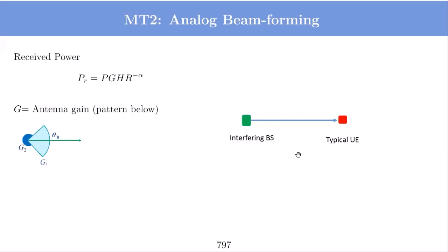Right, you cannot even have different frequency bands being formed in different directions. So analog beamforming: the way it is executed is you have a phase shift array, an array of multiple antennas, and you change the phase of each antenna, and depending on the phase shift, you will have beams in different directions. So that's done in the analog domain.